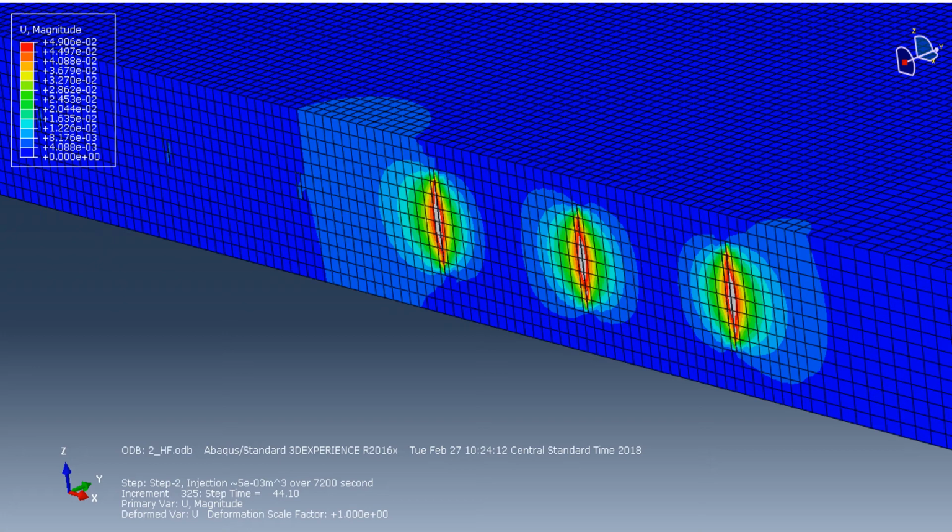Typical pump time for one stage is 2 hours, but to minimize computational expenses, we have set the pump time for each stage equal to 1 hour. The current 15-cluster simulation has gotten through the first 800 seconds of one 3600-second stage. From this point, we can already see the evolution of fractures and the stress distribution around the fracture.